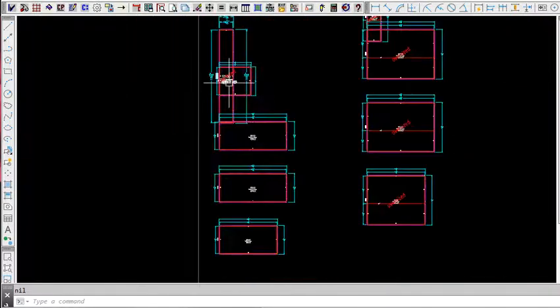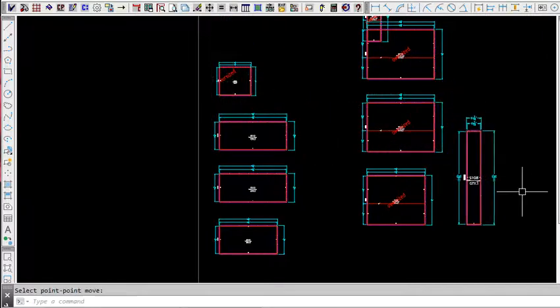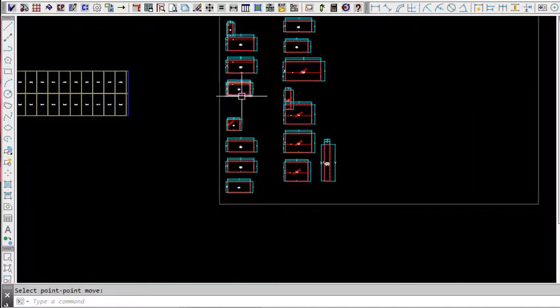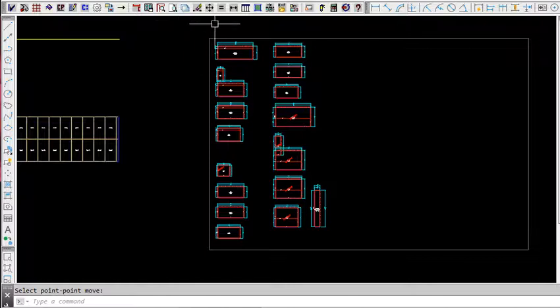And let's see if we can move this panel out of here. We have this move command right here that gets all the components of a particular panel, and then you can just pick a point and just move it. So it gets rid of the cluster. It's like the group utility in AutoCAD, but it's meant for anything with the same panel tag gets grouped over.